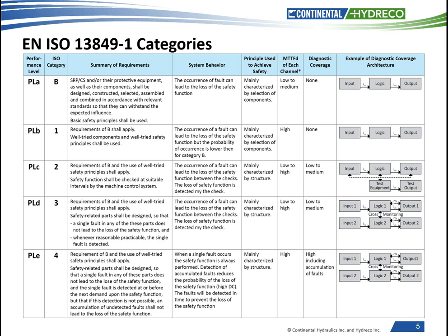The biggest change from a Category 3 is that multiple failures will not lead to the loss of the complete safety function, and it will not allow the reset function regardless if all the monitored signals show correct. Reset must be performed manually, an act of will by the operator manually verifying all the safety is being met.